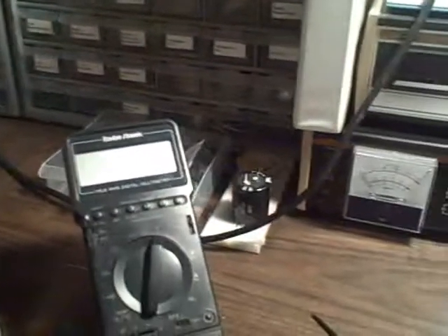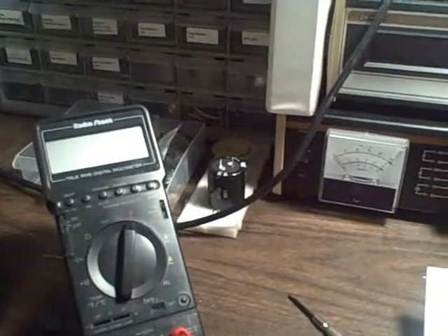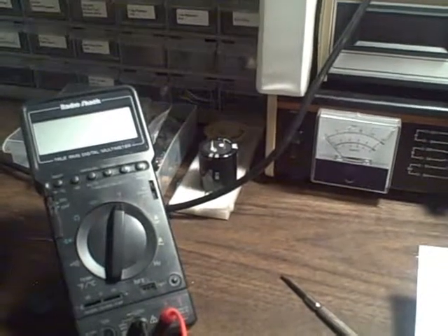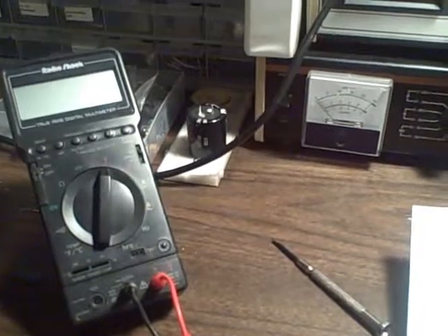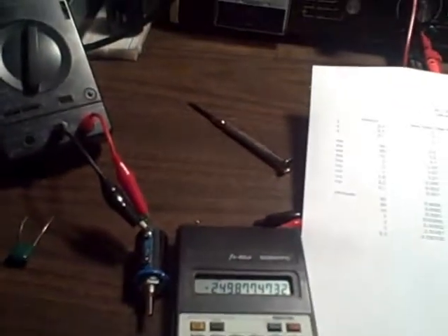Okay, so we just did the math here on our calculator, and we find that with the output being 0.3 now, where we started out at 0.4 volts peak, then we are running 0.3 over 0.4, take the log of that, times 20, and we wind up at a negative 2.5 dB, which is less deviation than the 3 dB point would be.